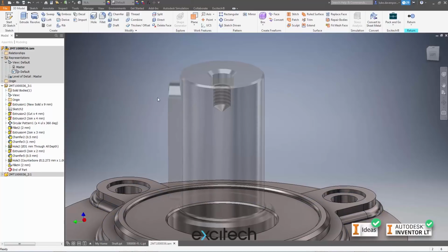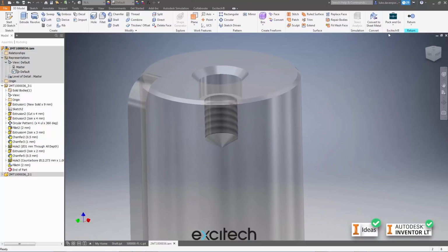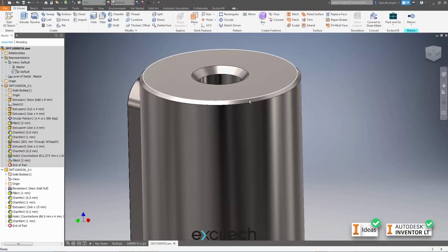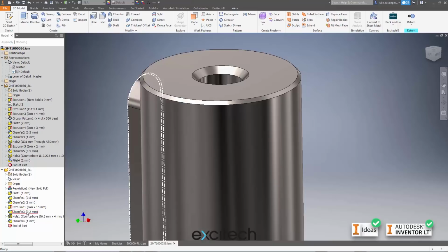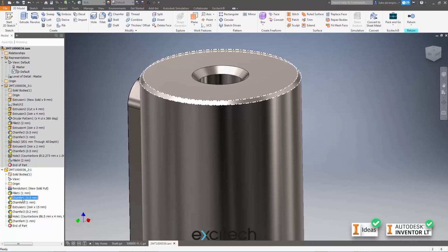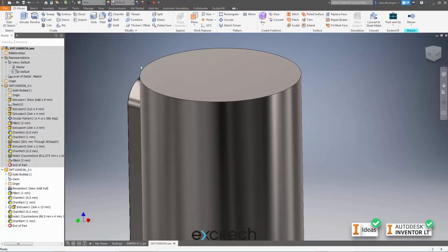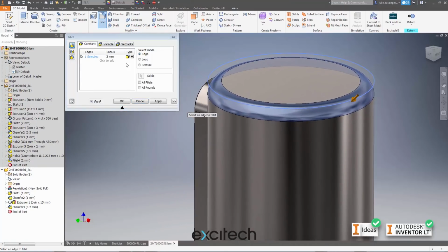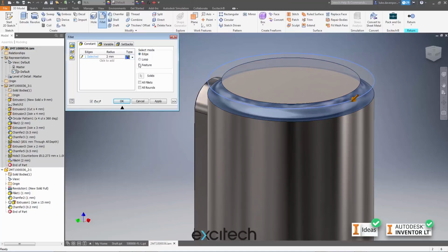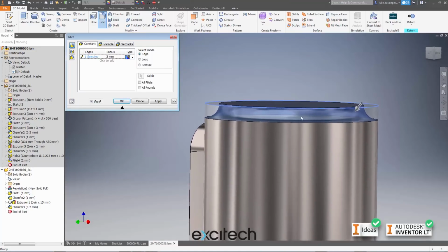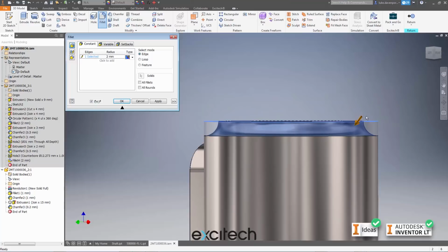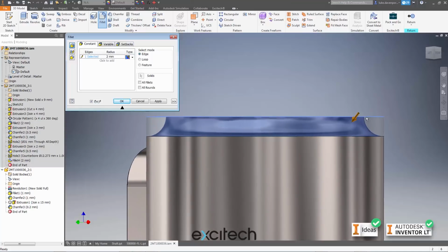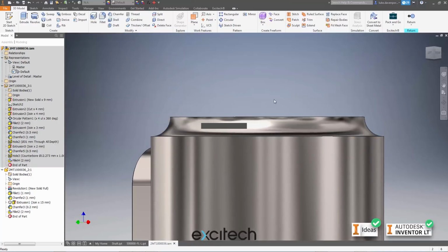And the inverse of that, if you've got an external edge here, if I hit return here and edit this part here, let's get rid of the existing chamfer on there, if I can find it. Let's delete that, and let's create a new fillet here. So that's a standard fillet, but if I do the new inverted fillet, that's almost giving me clearance for as if this part is mated to a part with a weld here. That would give me a nice clearance to the weld, even if the weld is a bit proud of 45 degrees. Okay, so pretty handy.